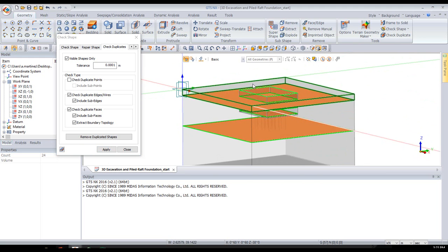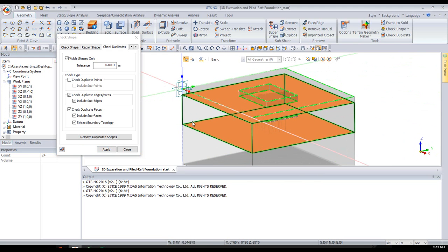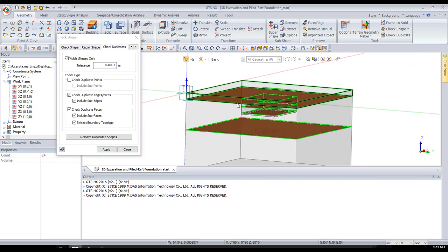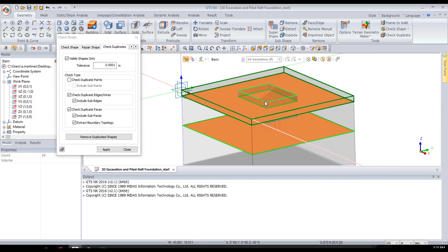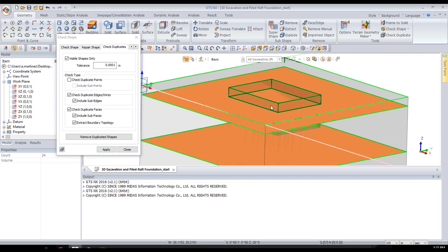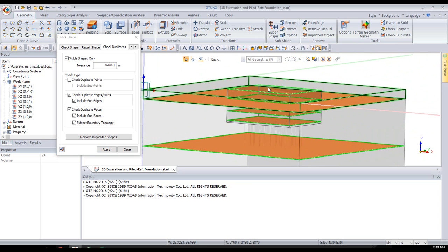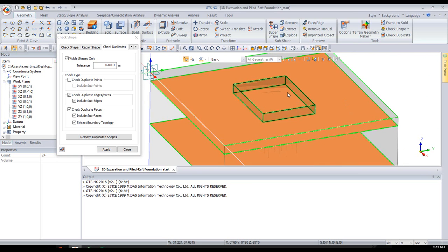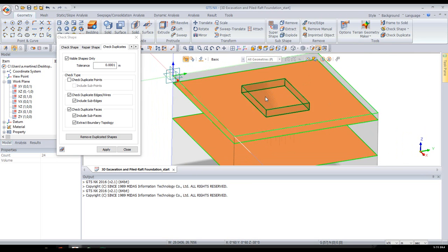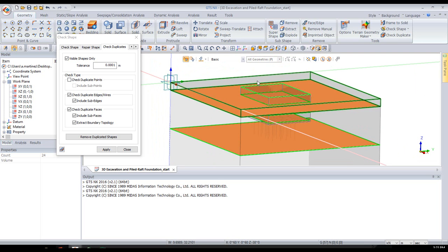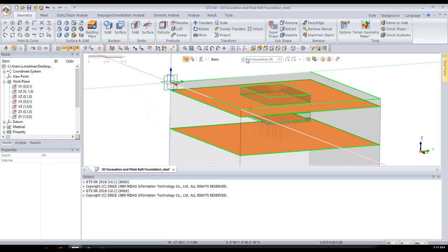So for instance here, we see that the faces in between layers and even inside are orange. So the program is going to connect these layers to each other. But the program doesn't have any of the vertical walls inside lit up in orange yet. So the program wouldn't be connecting the excavation to the outer soil at this point. We would have to correct for that.